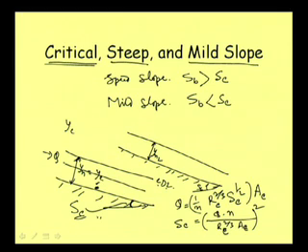And if we reduce the slope, then depth will go high. For steep slope we are getting lesser depth than the critical depth, and for mild slope we are getting depth more than the critical depth.